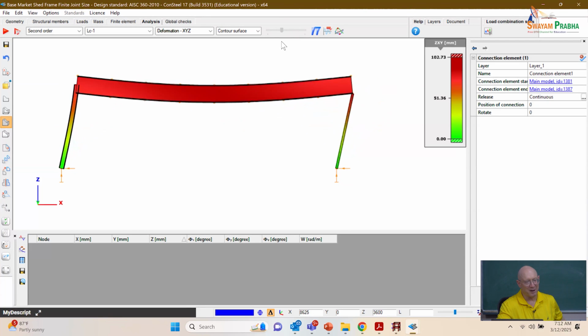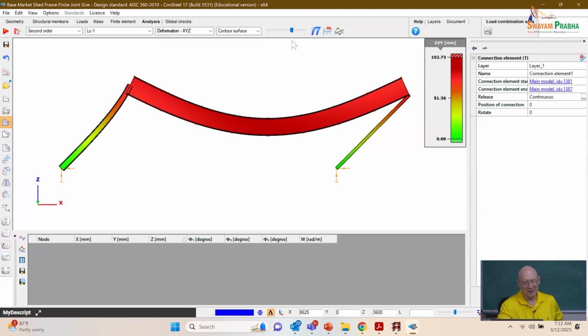If I'm connected to the bottom of the roof girder here, it's deflecting further, right? Because I've got a major axis bending rotation that's counterclockwise in the roof girder. If I'm connecting to the bottom, then that point's displaced over laterally further than the reference axis, right? So both of those things are giving me larger displacement at the top of the HSS column than that other model. You know, you might say, well, does that make that big of a difference? It doesn't make too big of a difference, but it is a difference. Okay?